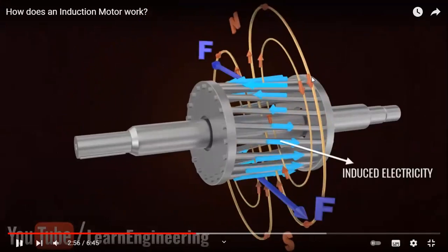So the same thing happens here. This is the rotor of the induction motor. We did not supply anything to the rotor; we just supply the stator field winding. When you supply the field winding, one rotating magnetic field is there. When we put a coil or the rotor in the rotating magnetic field, earlier we inserted a coil. Now if we place this cage rotor coil in the rotor, what will happen? One EMF is induced. When the EMF is induced, current flows into this rotor arrangement, this coil cage rotor.